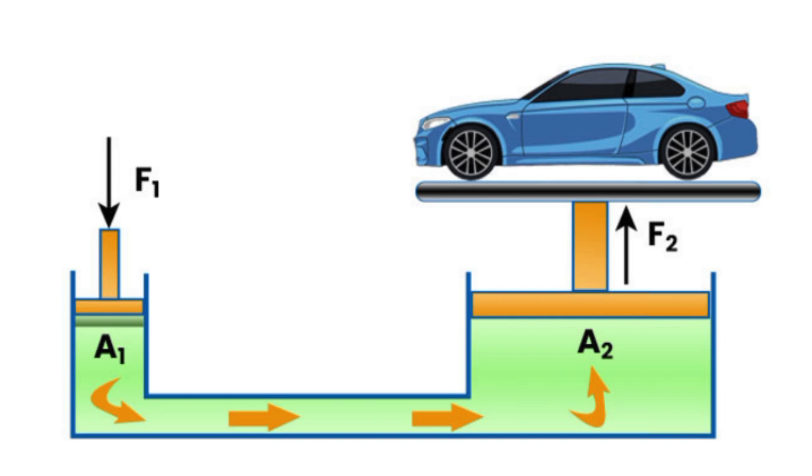Notice that the pressure applied at the piston is felt not only at that point, but also at every other point within the fluid. The fluid particles exert equal pressure on each other, which means that the pressure is transmitted evenly through the entire fluid. This leads to the key idea that the force or pressure applied in one location can be transferred to another location within the system.